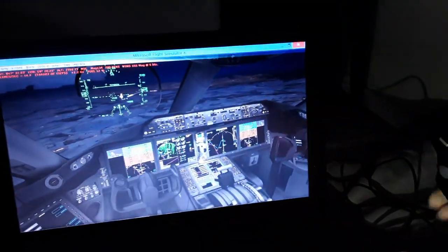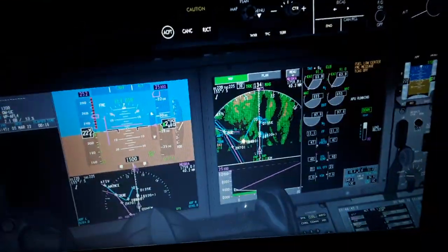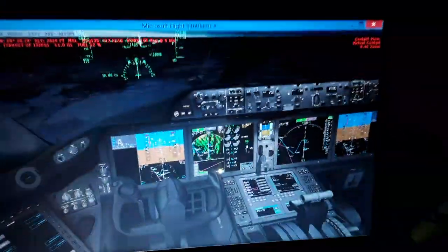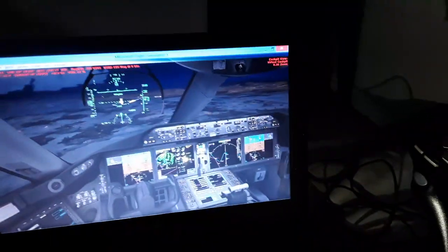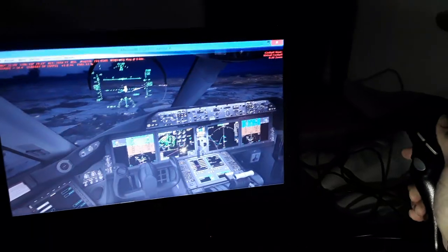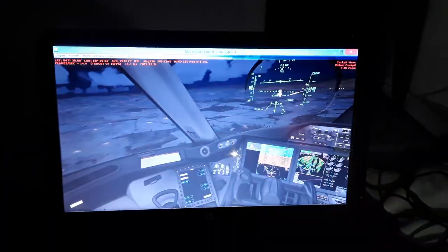Pitch trim up a little bit. You can see the LSZH localizer here. We have all the indications from the LSZH localizer as we are approaching: airspeed, altitude, radio altitude above the ground, how many feet above the ground we are. So we need also maybe a little bit more and less thrust from time to time.